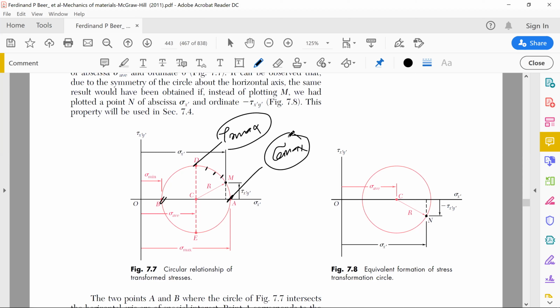And then we will say as an engineer that this design is safe if your allowable sigma and tau values, because of that particular combined loading applied on the beam, are greater than the calculated values, so you are safe, otherwise you are not safe. So the prime objective of this Mohr circle is to calculate maximum sigma values and maximum tau values so that you can compare them with the allowable limits. And if your allowable limits are below these values, you are not safe. So your work is not done when you calculate sigma only at any particular angle using the equations, right?